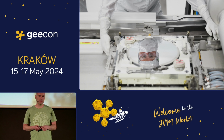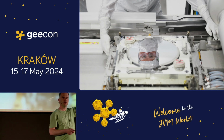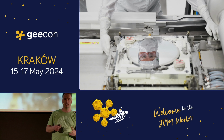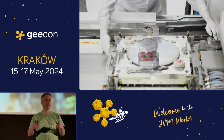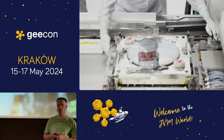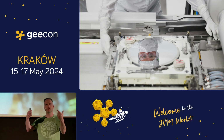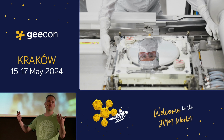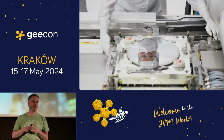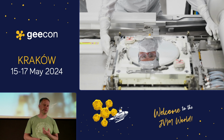And then that wafer goes on the wafer table, the thing you see here. Normally people aren't looking at it. It's an automated process. And the wafer is actually floating on that wafer table. It's a magnetically levitating wafer table. Because if they would clamp the wafer, it would already bend a little bit, which results in less functioning chips. So we do everything to make sure we produce as many functioning chips as possible.